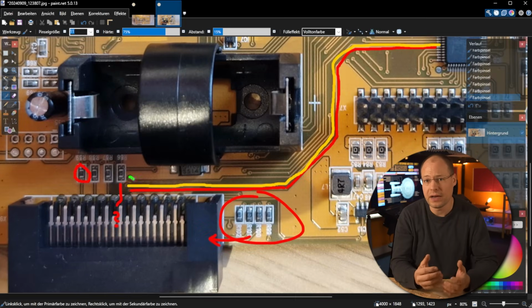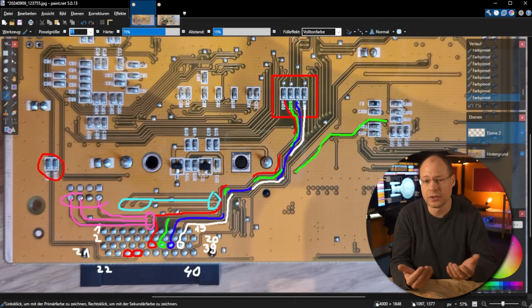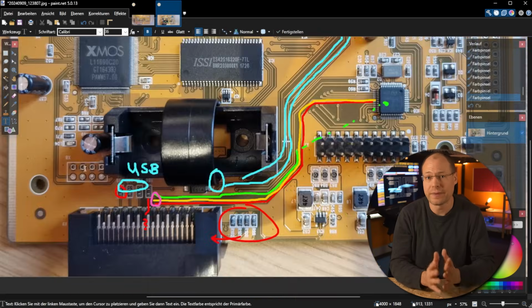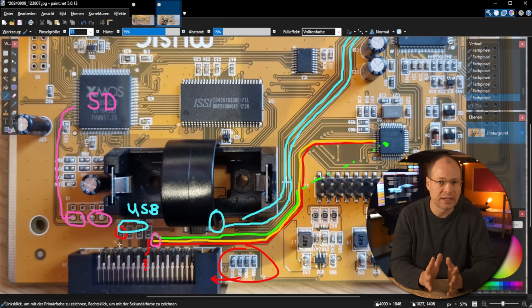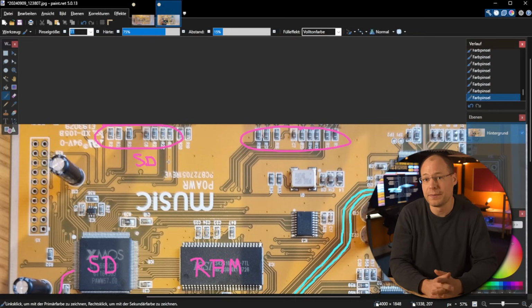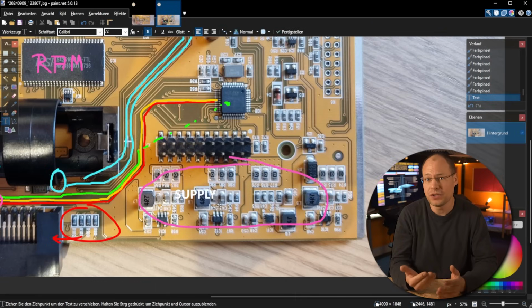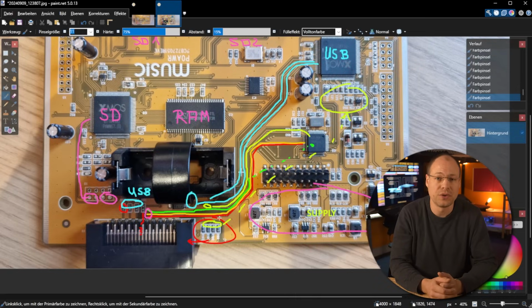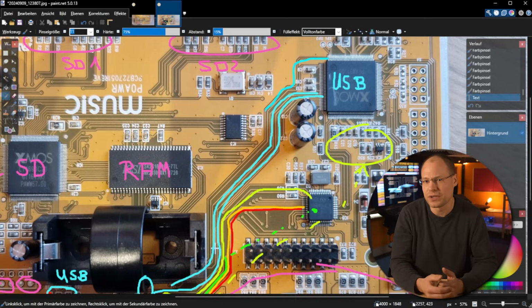Presumably, 4 of them are an I2S-like connection plus the necessary bit clock and frame sync clock, hopefully. I2S actually only supports 2 channels, but UltraNet had already transmitted 8 channels here. In addition to I2S, there is also TDM, which officially supports more than 2 channels, so it makes sense to start with TDM here. As we can decode the signals later in the FPGA, we are not making a big mistake here if we are dealing with other types of signals if my assumption is wrong.